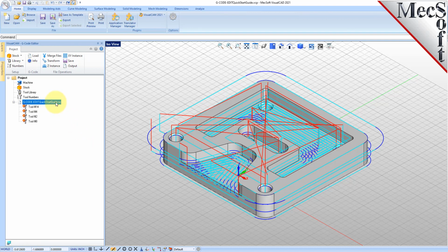That's because in your tool library, you may have multiple tools with the same tool number. In your shop, you may have hundreds of tools, according to your standards, the way you apply your toolpaths and your tools. You may have more than one tool with tool number 1, say. So you define a tool crib with a subset of those tools in the library and assign tool numbers to them, and how they appear in the tool crib is what will be selected from when you load a G-code file that references tools.